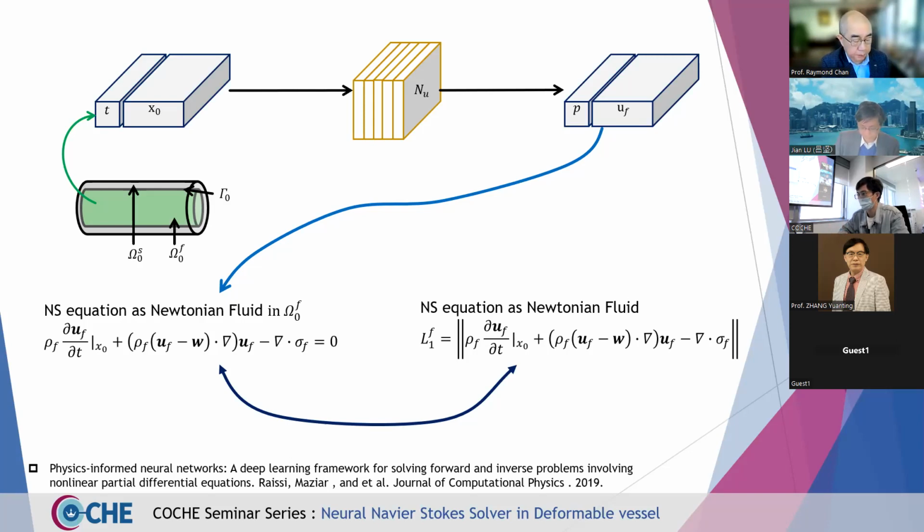the fluid speed. As we discussed just now, this speed should satisfy the Navier-Stokes equation because it should be based on physical law, right? The physical law is reflected by the PDE here, so it should obey this equation. Conventionally we use finite element to do this, but here we use a neural network to replace it. We input the coordinate into a neural network. The neural network is a function, and it outputs a result, which is u. The u should satisfy our PDE.